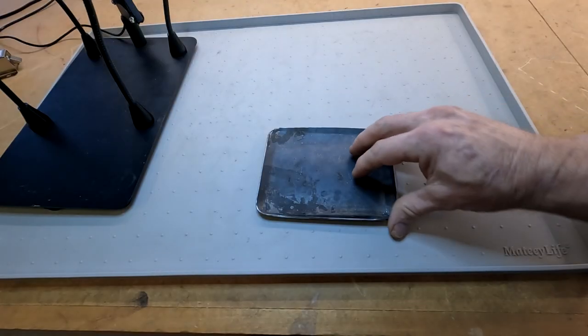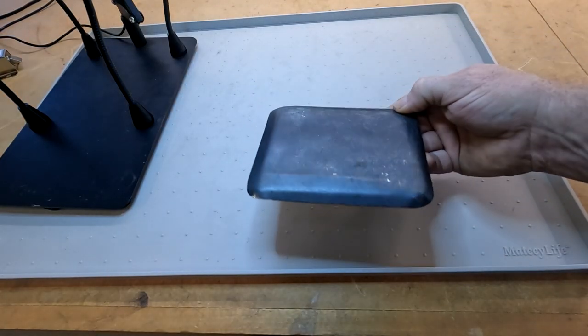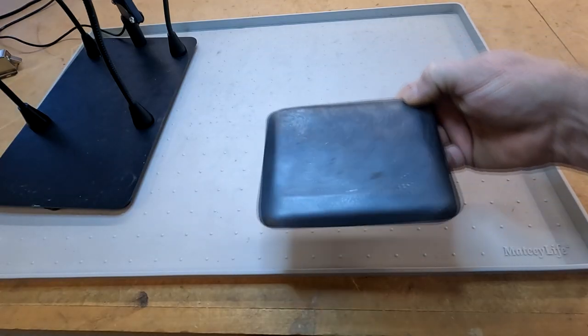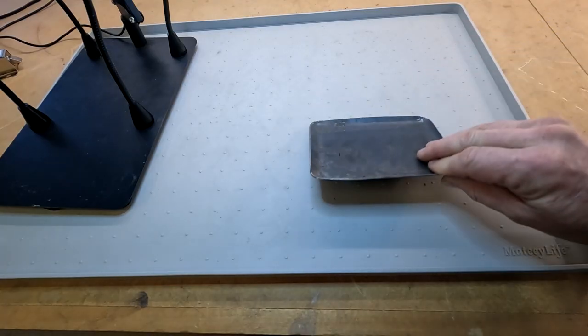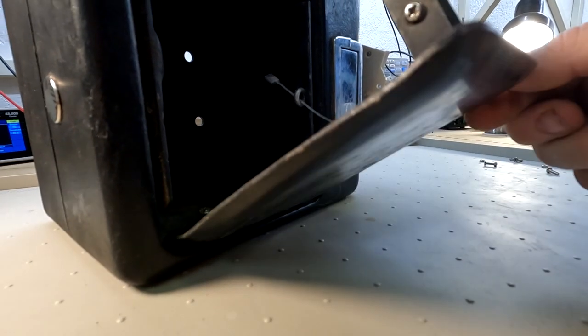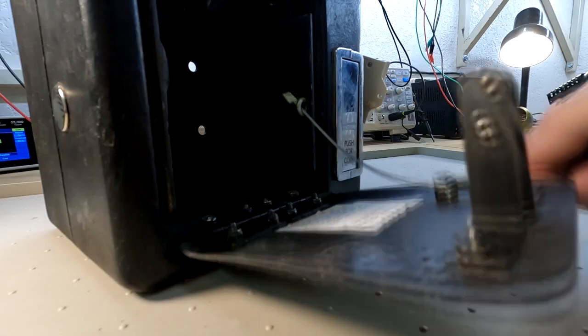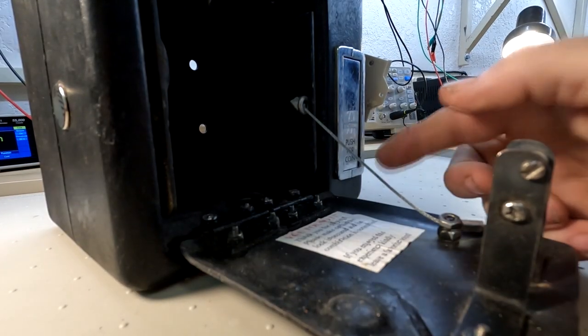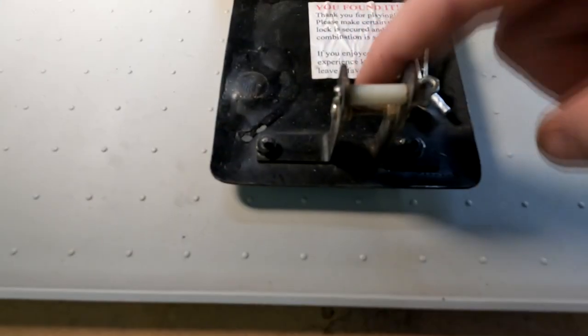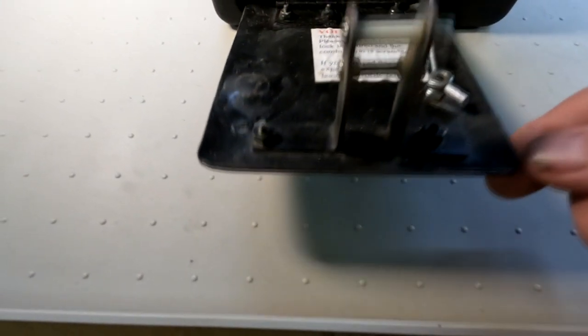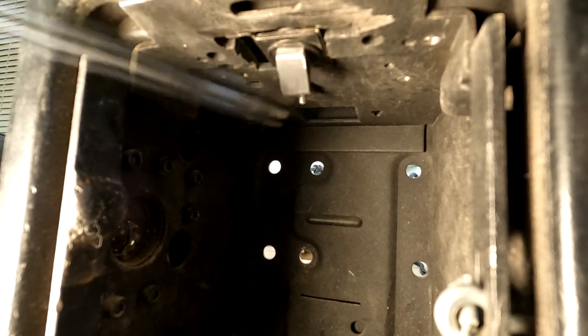A new coin box cover was made from 1/8-inch sheet steel. The edges were bent over and carefully shaped with a hammer to look like the original. A hinge was installed so that it will fall open when a solenoid latch releases it. A small cable was added to prevent the door from opening too far and damaging the hinges. An extended arm was added with a nylon sleeve which hooks on the retracting solenoid.